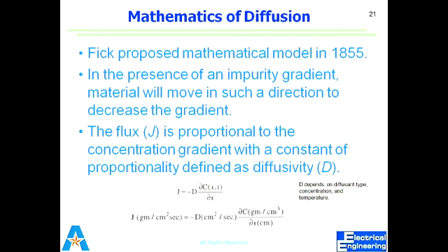it goes even deeper. The important thing here is that in every case, the area under the curve is always constant, because the area under the curve shows the total number of dopant molecules, and that is constant in driving. So in driving, the area under that curve would always be constant; it's just that the surface dopant is moving into the wafer.